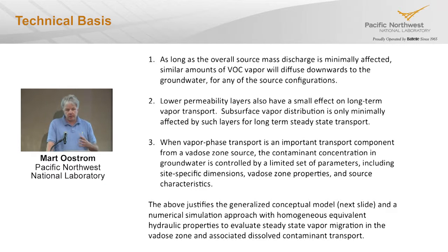But what we noticed is that as long as these low permeability zones have a reasonable amount of available gas phase, so that the VOC vapors can actually transport through diffusion to these zones, they're not really forming barriers to vapor transport. So although this is a uniform system, the way it's depicted, it can actually represent a layered system for that matter.